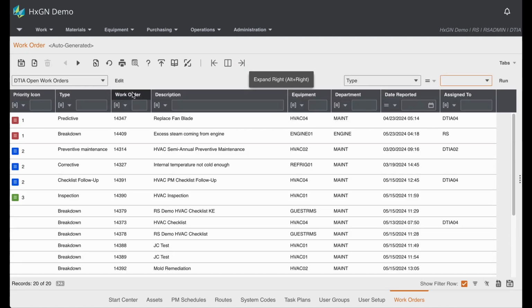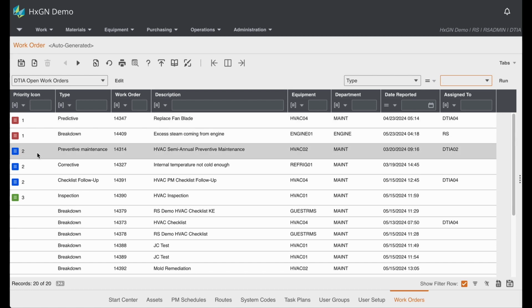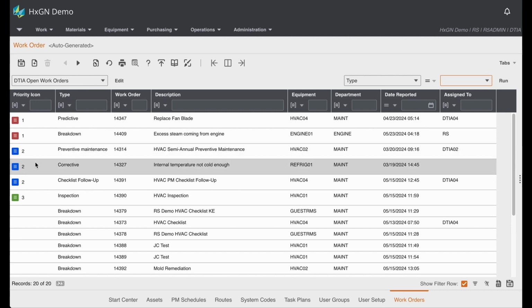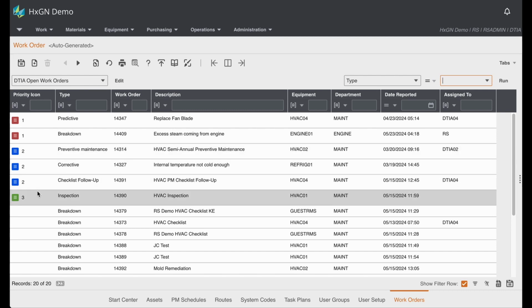Now, on a final note, the importance of work order priorities can be applied to setting priorities in general. It is easy to become overwhelmed by the sheer volume of tasks and responsibilities we face daily. The same is true for a technician logging into an EAM mobile app and viewing a list of work orders assigned to them. Assigning a priority code for each work order aids in time management and focus. This can improve plant reliability and maintenance efficiency.